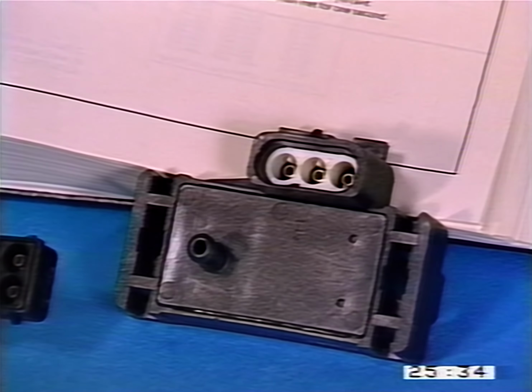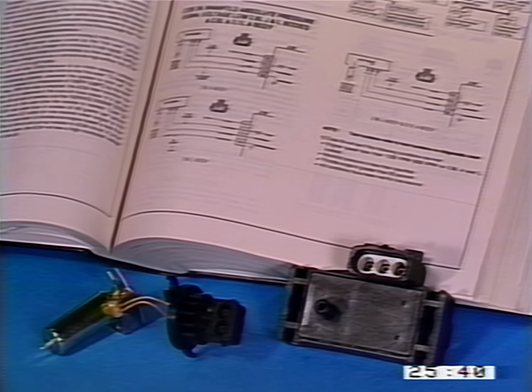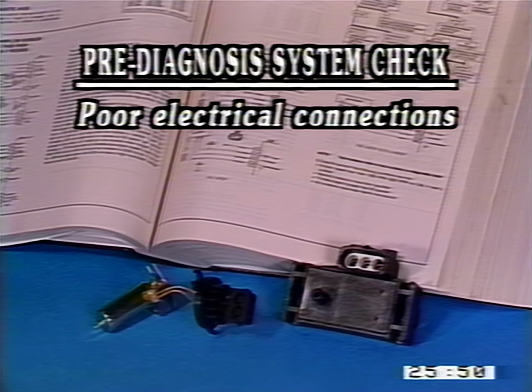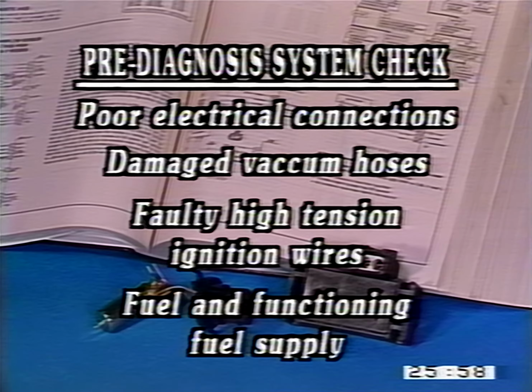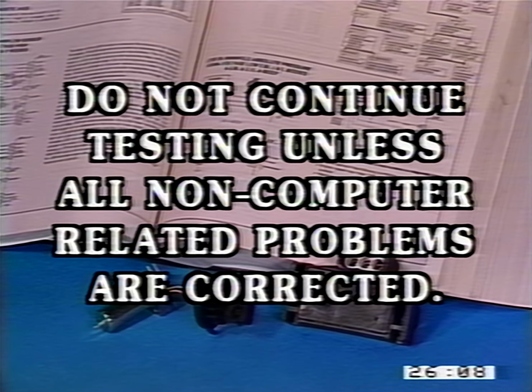The key to diagnosing computer-managed vehicle systems is the elimination of fundamental sensor, solenoid, and wiring problems before considering the computer and PROM as a source of operating problems. Prior to any formal diagnosis being performed, the vehicle should be checked for poor electrical connections, damaged vacuum hoses, faulty high-tension ignition wires, and fuel and a functioning fuel supply. Troubleshooting these systems involves making sure that all engine systems not controlled by the computer are functioning properly. Do not continue testing unless all non-computer-related problems are corrected first.